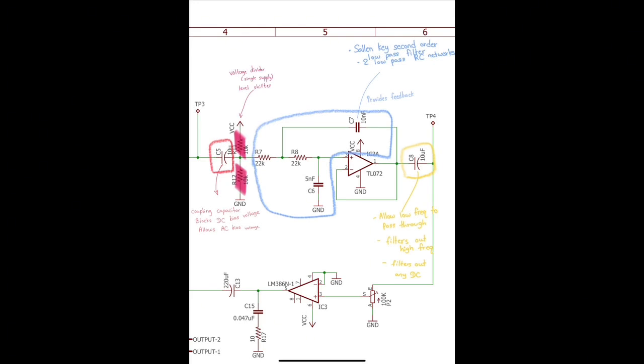Capacitor C8 is connected to the output of the filter. It serves the same purpose as capacitor C5, blocking out DC voltage in the output before sending it to stage 4. Stage 3 is important as it cleans up the signal and prevents unwanted noise from being sent out, and ensures that only the clean filtered signal gets amplified in the next stage. This removes the junk and highlights what really matters in this biomedical signal processing system.